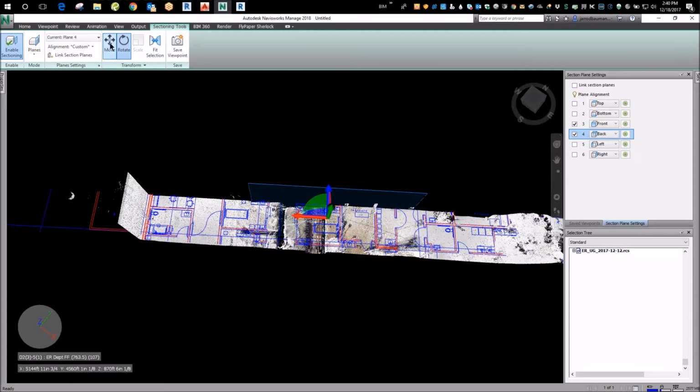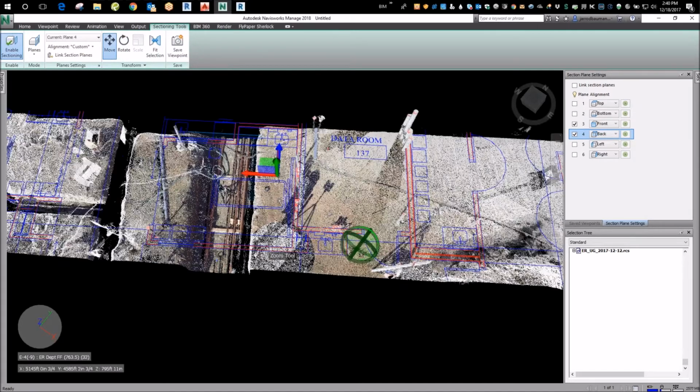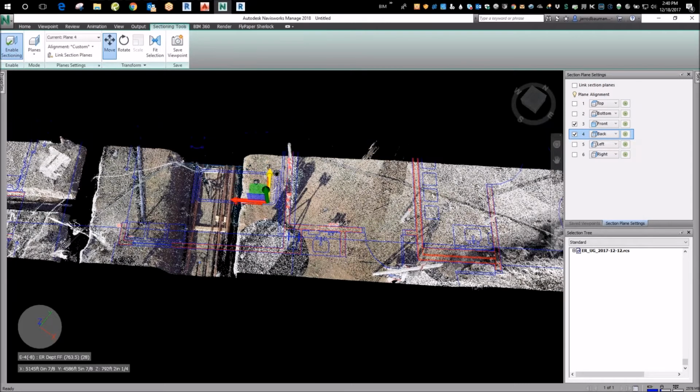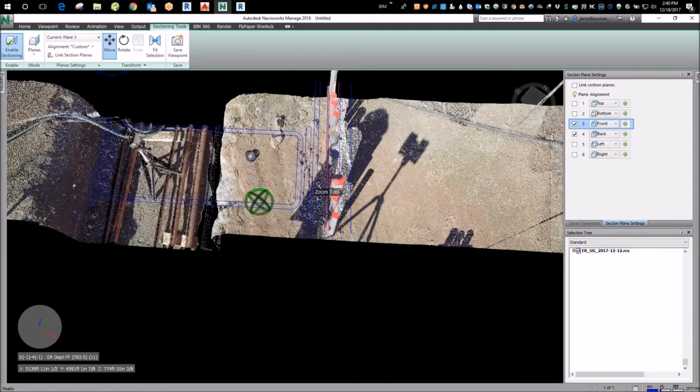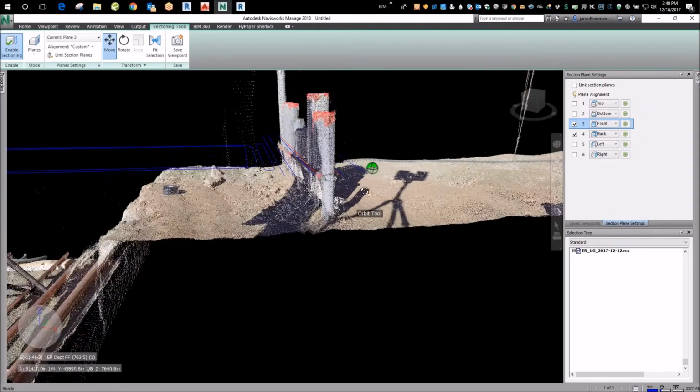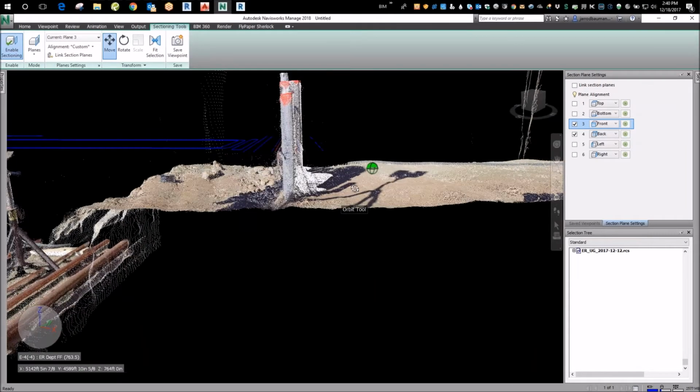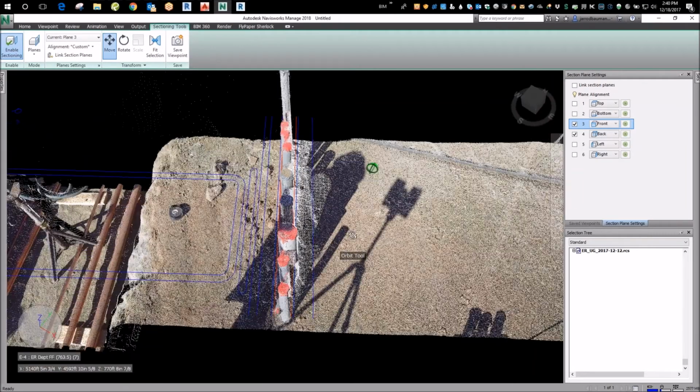here. And then you want to switch back to the rotate or the move, right? When you're done, you don't want to rotate anymore, so switch back to move. And you should be able to bring it down to where you can look just like at a single set of conduits here. Right, you can pull this in and look at just one wall of conduits, and it makes it a lot easier to see when it's like that, right? You can see those red lines. You can tell right where you're at.